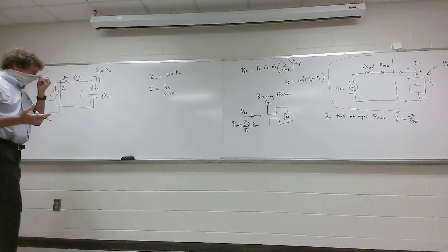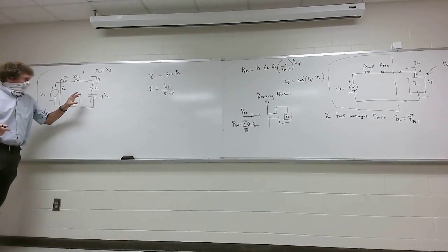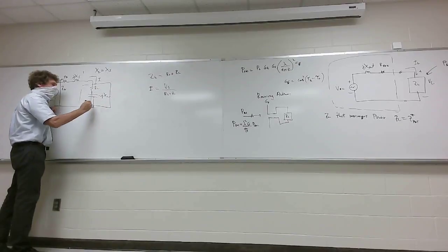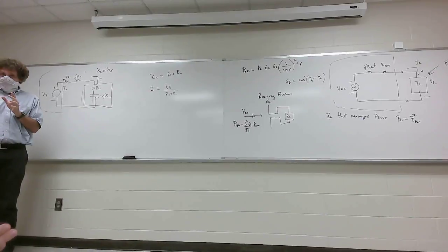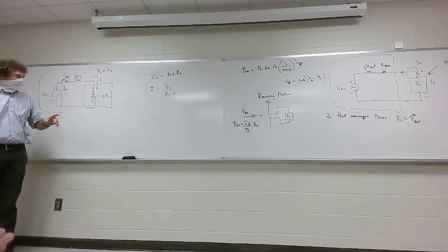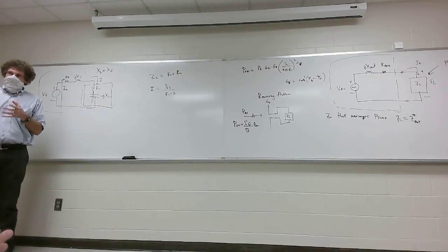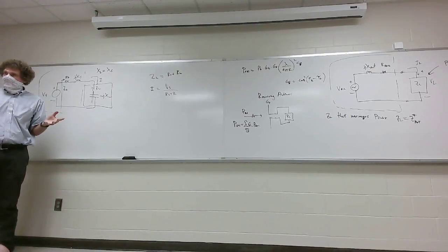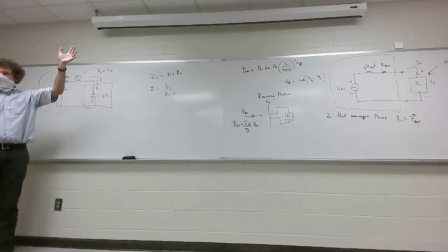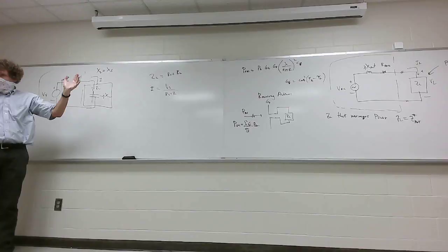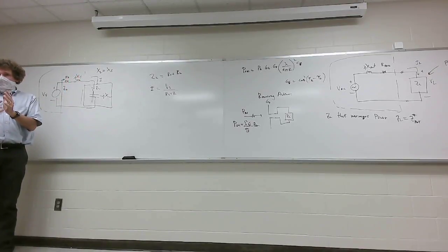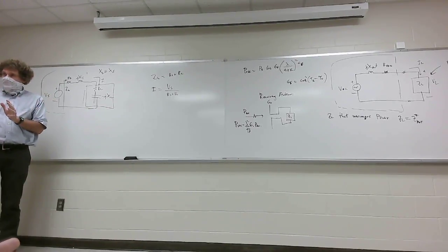And what would the power be dissipated in the load? This is real power. I could calculate the voltage, right? But do I need it? How much average power is dissipated by a capacitor and inductor, class? How many know it's 0? A capacitor can't dissipate power. It can store energy and bring energy back. That's called reactive power. An inductor can store energy and it can't dissipate it. Only resistors can dissipate power as far as passive lumped elements. Y'all follow me on this, class?